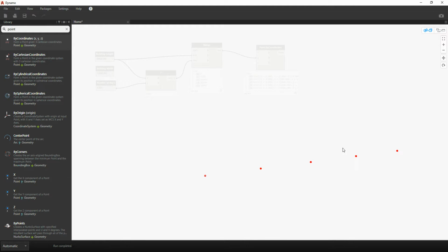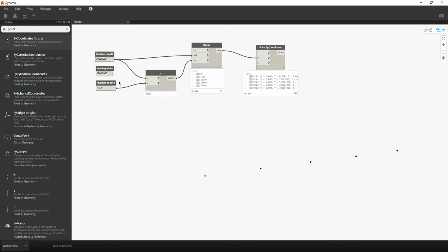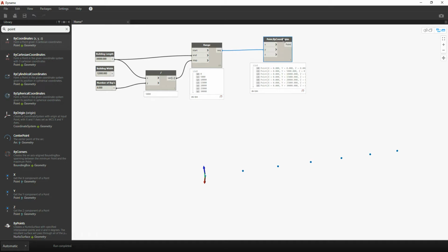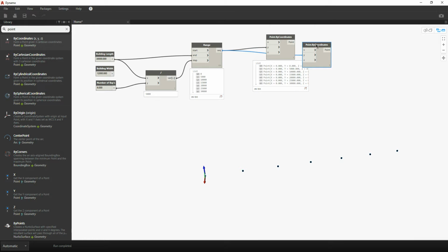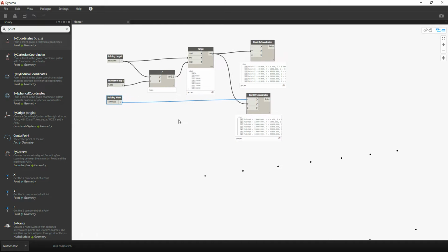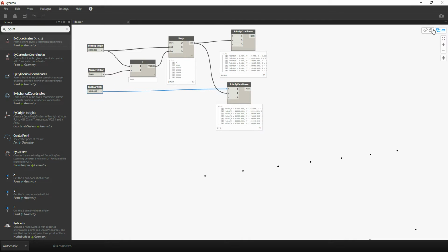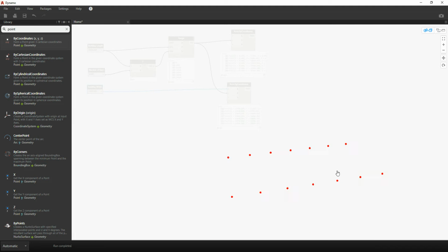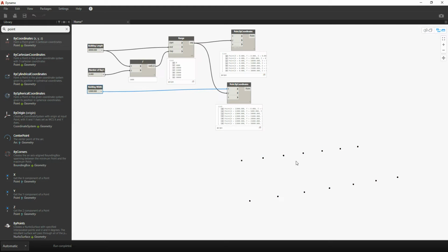So just looking at sort of side on there. So let's put that back to 6. So we've got one set of coordinates, and you can see this is where that sort of UCS icon attaches itself to that point. So we're going to copy paste that again. But we can do our building width now of 12 meters in the X direction. You can see there's our building laid out. So they're the base points of our columns.